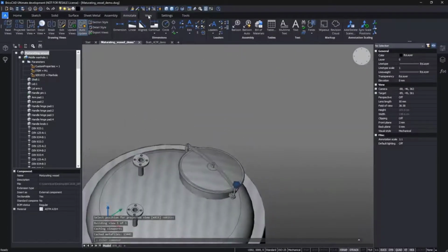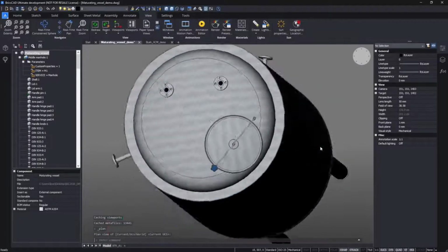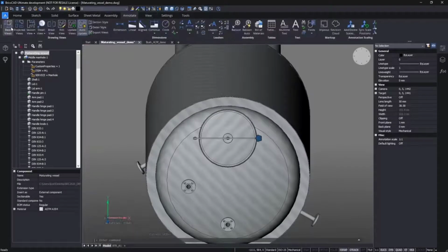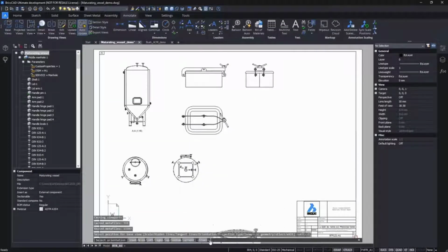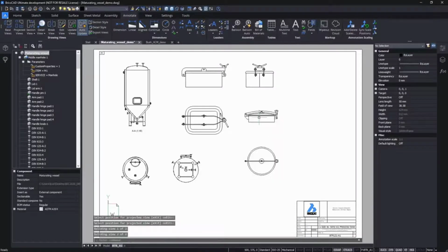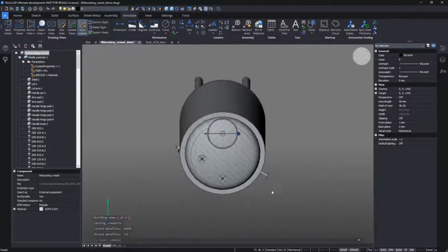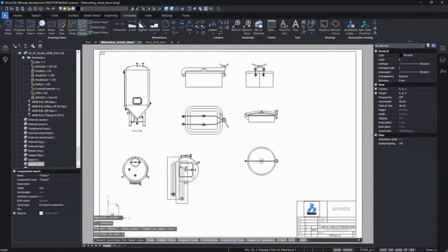The next step is not so obvious and could take some time because of subassembly orientation. It's not aligned with the coordinate axis. That's why, to create the correct view of the top manhole, we use the view-based command with current orientation options. These options inherit the camera position from the model space and use it in drawing views. It allows us to create custom views quickly and easily.